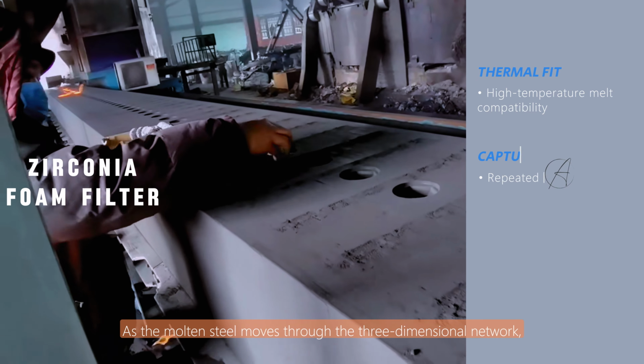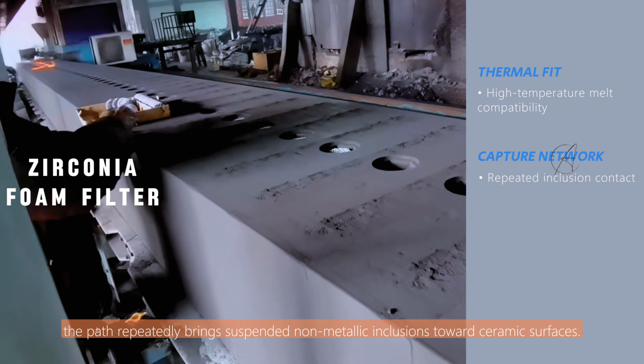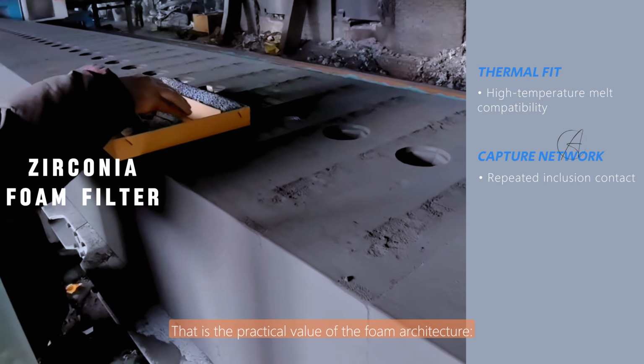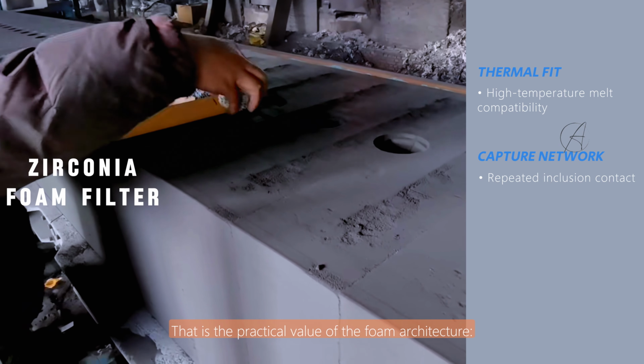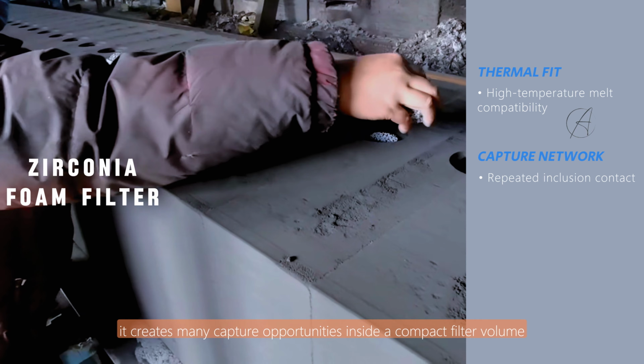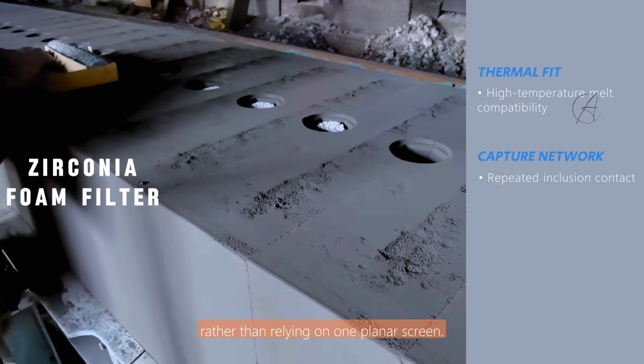As the molten steel moves through the three-dimensional network, the path repeatedly brings suspended non-metallic inclusions toward ceramic surfaces. That is the practical value of the foam architecture. It creates many capture opportunities inside a compact filter volume rather than relying on one planar screen.